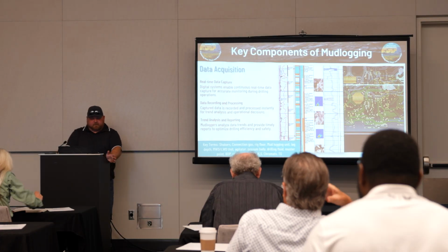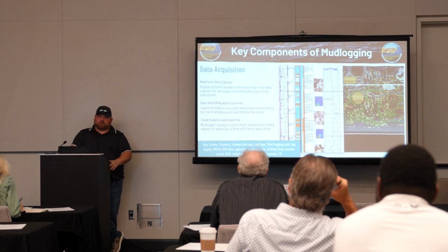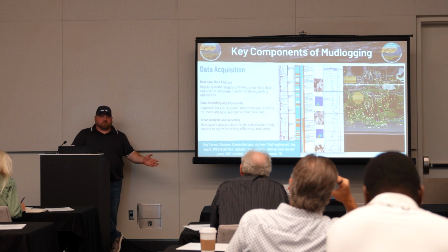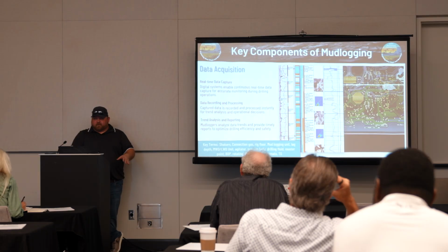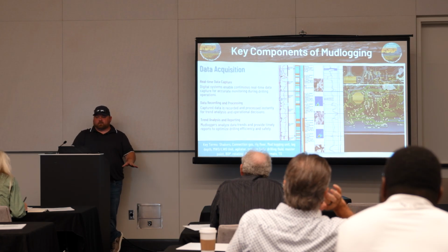Building a mudlog, data acquisition, this is where everything's going to go. Like I said earlier, the mudlog is a one-stop shop for any and all information on that drilling location. The only thing you're not putting there is pipe showing up. Everything that has to do with drilling parameters is going on the mudlog.